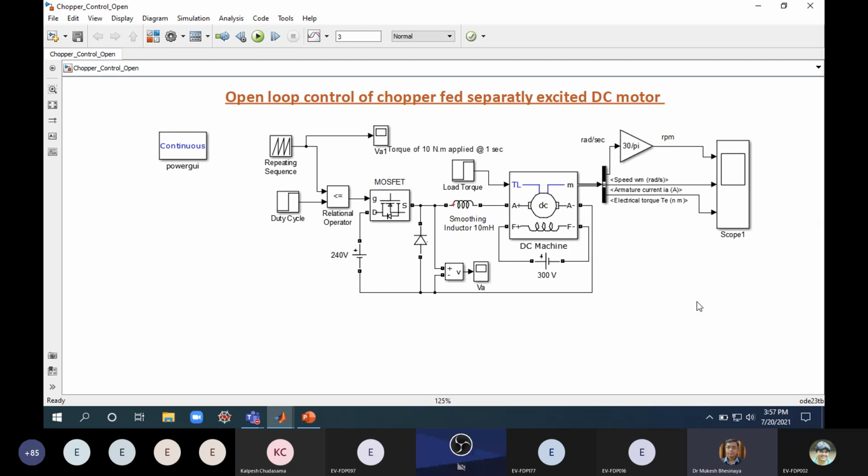I forgot the exact name. The rated power was very high, around 45 kilowatt or so, with a torque of more than 300 Newton meter. The transmission in that was a fixed gear. It also depends upon the type of motor, as I already mentioned, whether you are going for a fixed gearing or you have other mechanisms. Forward and reverse actions will be achieved by changing the direction or by changing the voltage with the use of a converter.